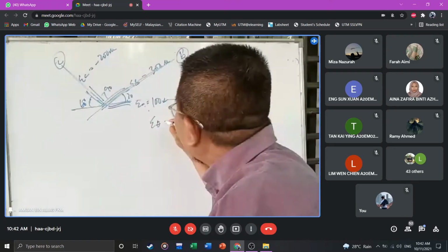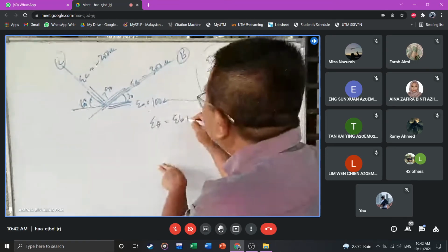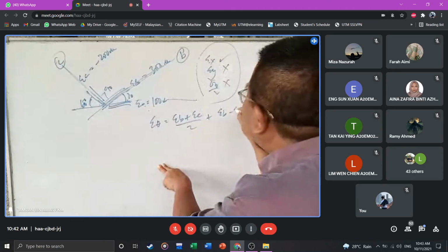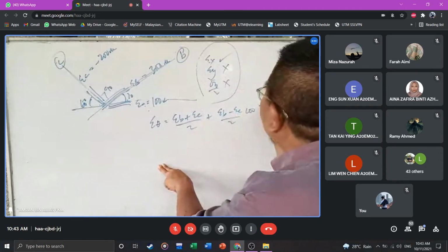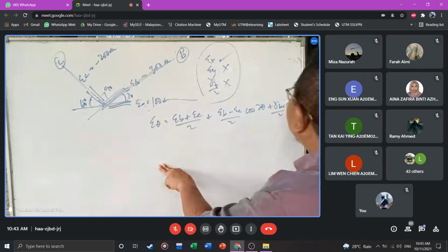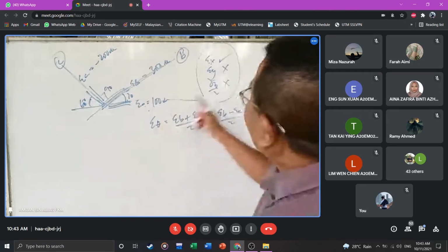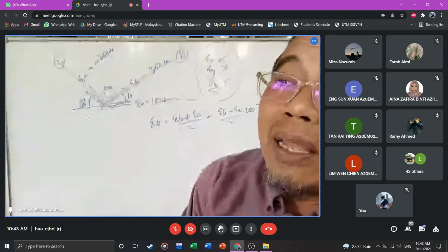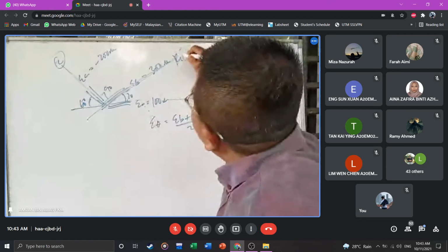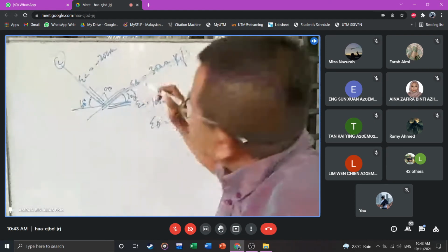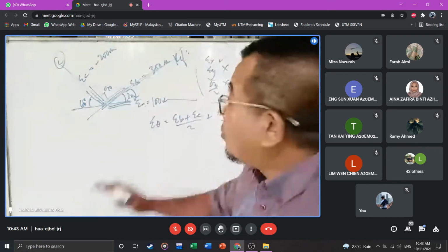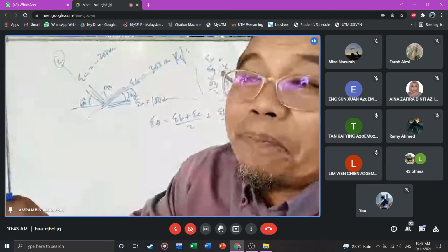E theta is equal to EB plus EC over 2 plus EB minus EC over 2 cos 2 theta plus gamma BC over 2 sin 2 theta. So you start with axis B and C. Your angle is from that one, not from X anymore.